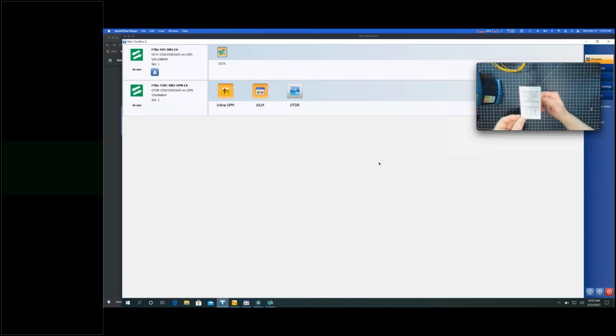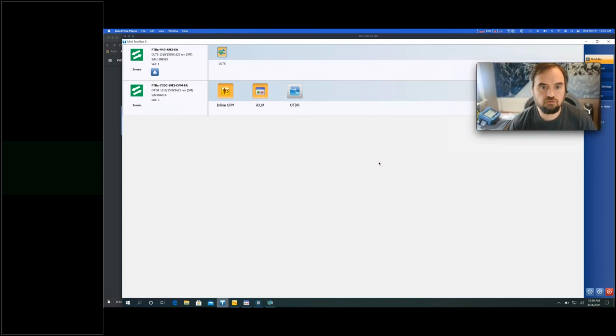On the back, of course, scope clean scope, we've got the attenuation at 1310 is 0.35 dB, and at 1550 it's 0.25 dB. Basically that's the purpose of having that reference on the back of our business cards. So we know that there should be greater loss at 1310 than 1550.